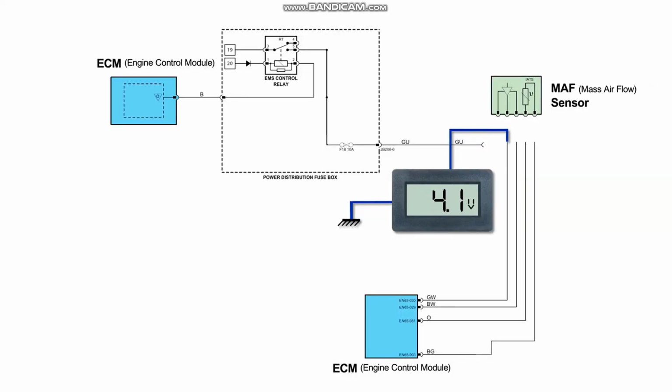Again, a low reading would indicate a resistance which would be checked by following the circuit back to the module. If the voltage at the module connector is still low, then the module connector or the module itself will be the cause. An acceptable reading will indicate a problem between the module connector and the sensor connector.